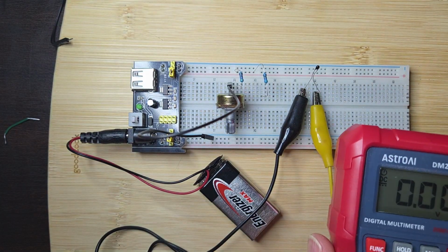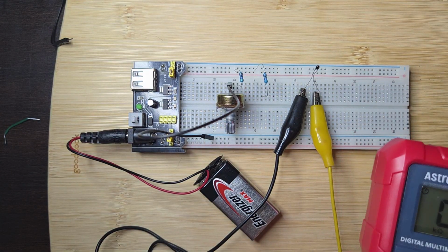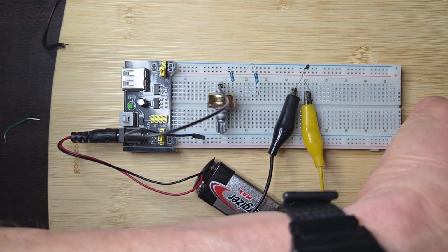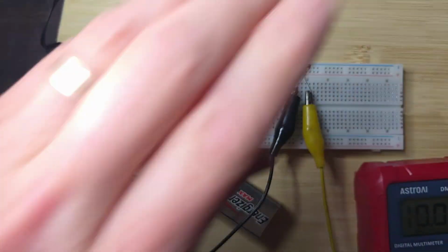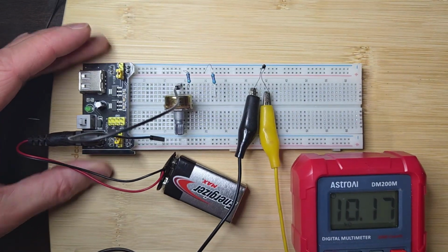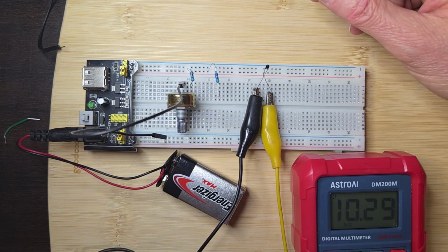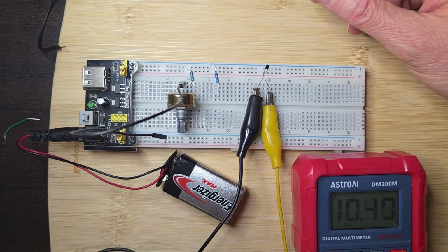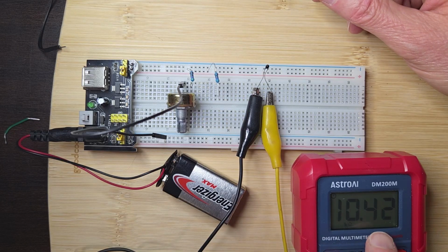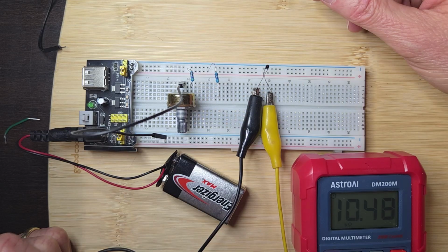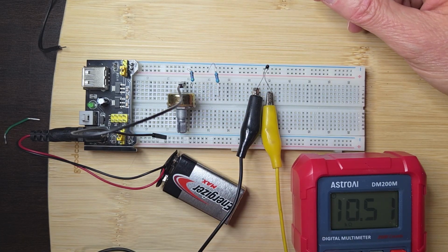So that's all good. This is my ohm meter now, because I'm measuring resistance. I don't want to be measuring voltage, because what I'm trying to do is just show you how the resistance is going to change. So I'm just sitting here by itself. Right now I'm measuring, like the other day it was like 12, right? But it's a little above 10K. So I had that 10K pot that is too small. I can't balance it.